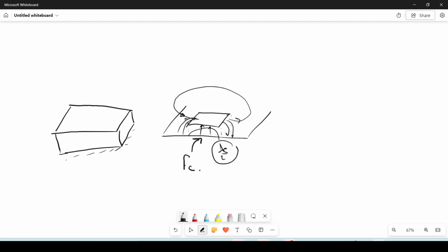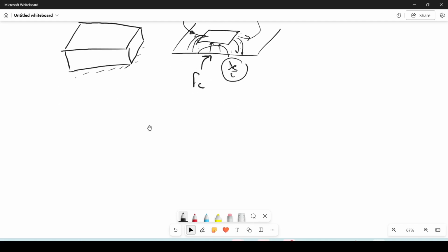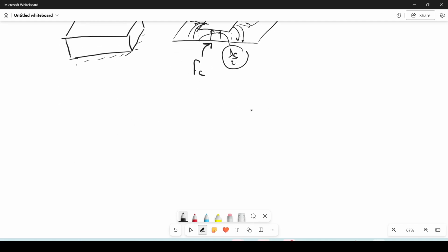So anyway, how to decide this lambda guide, the wavelength? The problem actually reduces to how to calculate epsilon effective, right? What does it mean? If I have the patch like this, and it sits on a material of epsilon, with height H, the substrate, and then this metallic patch is relating to the far field, right? So what is the epsilon effective of this medium?